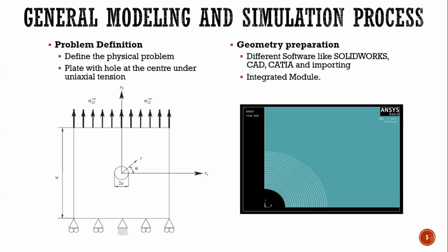This is a very simple problem, a plate with a hole at center, but sometimes we want to go for geometry which has a number of nuts and bolts and different complex parts, and they're joined together, and then we want to analyze them. Then it becomes very critical to prepare that geometry into an integrated module of any finite element package.